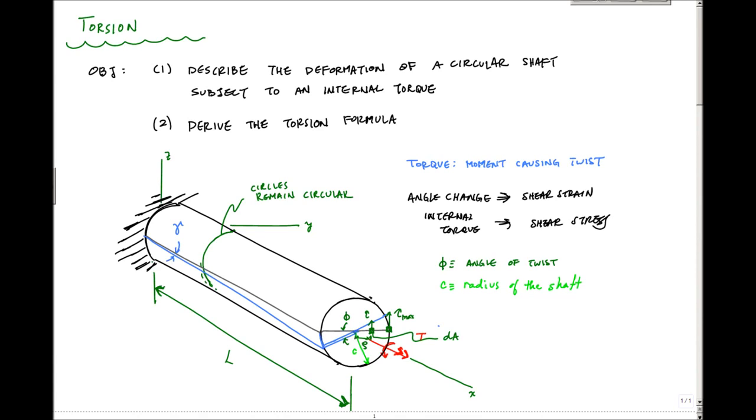And here you've got this relationship going on. We know that the deformation going along the radius from here, where it's 0 deformation at the center line, to the outer edge where it's the maximum deformation, is varying linearly. So we have this intuition that the shear stress along the face here is also probably varying linearly.